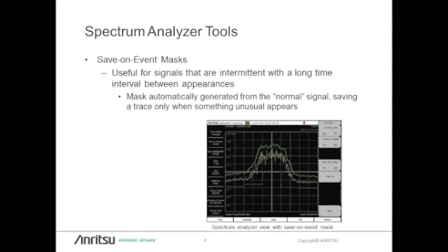So some of the spectrum analyzer tools that we're looking at are for pulse signals, and when I mentioned radar type signals, that's one type of pulse, but you can look at pulses that exist over a longer time frame. One of the things you can do is set up a spectrum analyzer remotely, hook it to Ethernet, and look at the time periods when a pulse may violate a certain threshold. You could actually have very sophisticated limit lines or just a single limit line. When it violates a threshold, you record the time, and then you can identify certain kinds of patterns for the interferer.